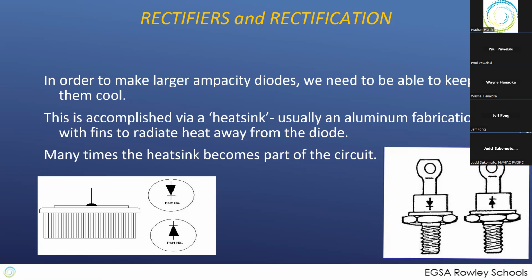So when we put a heat sink on, it's usually aluminum because it can radiate the heat away from the diode. But unfortunately, the stuff that insulates from electricity usually is also a good insulation for heat flow. So as thin an insulation as possible is used between the heat sink and one side of the diode. And over time, this insulation breaks down, especially if, despite having the fins on it, the heat dissipation wasn't sufficient.